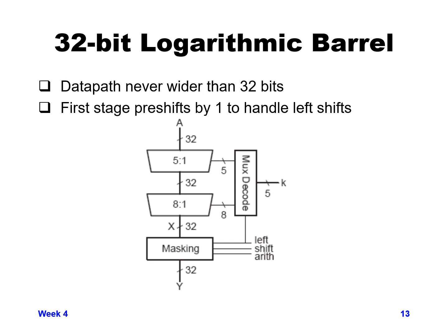And then we can choose whether it's a left or right rotation based on the logic that we talked about on the previous foil. And then finally, the masking bits on the bottom will handle whether it's a rotate or a shift, and determine the number of bits that come out. Again, I'm not going to go into the details of exactly what each of those stages looks like.